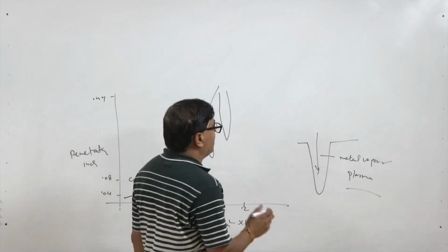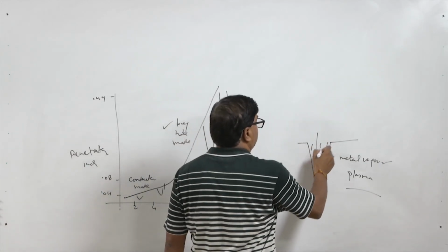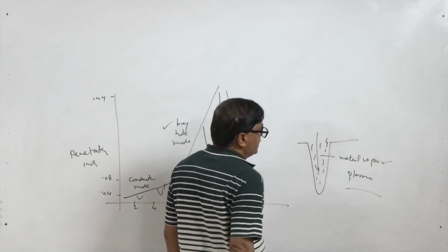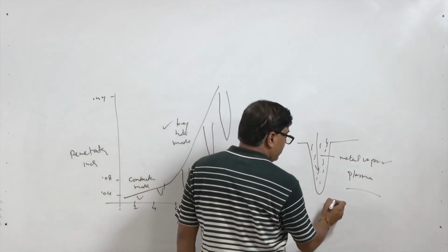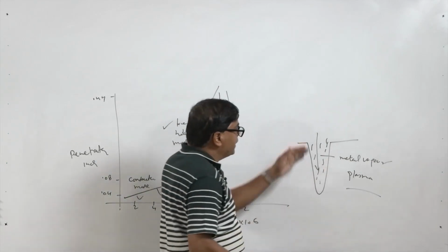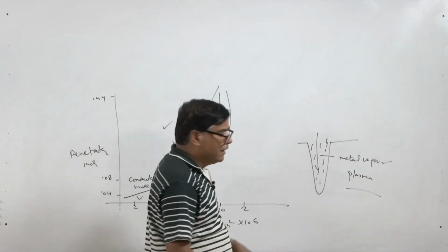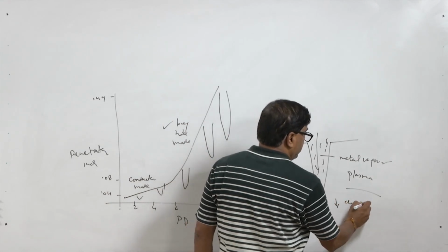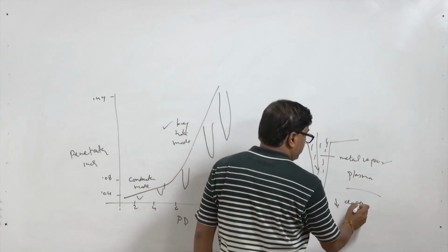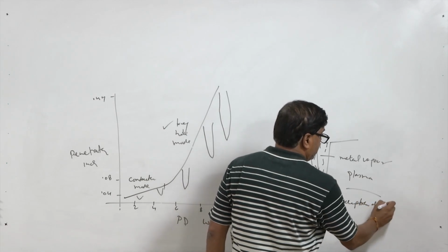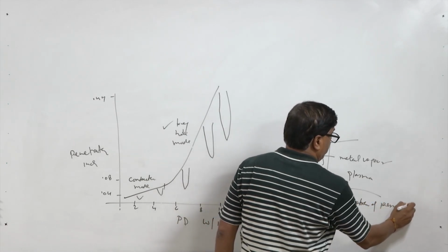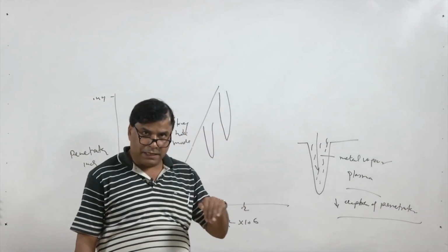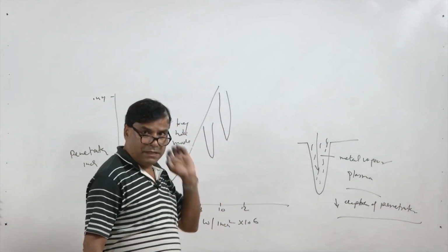So, whenever plasma is formed in this gap, it absorbs the laser, which in turn reduces the actual energy delivered to the base metal, and that in turn reduces the depth of penetration. So, this plasma formation must be taken care of or suppressed.